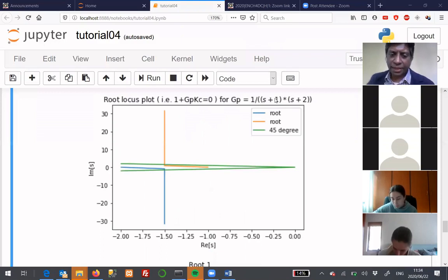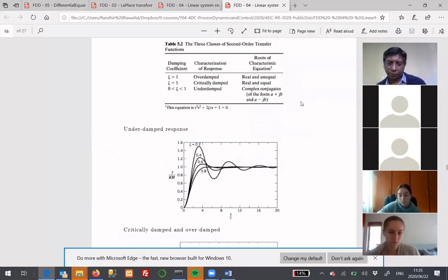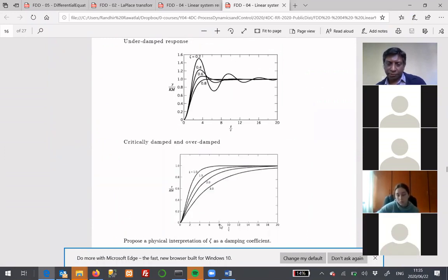And we'll see later on that a good criterion for this, a nice balance between those extrema, is given by these green lines here. These green lines are actually 45-degree lines, and you'll see why if you read back in notes 4 or watch the video for notes 4. The 45-degree lines correspond to the first oscillation, the first overshoot here.